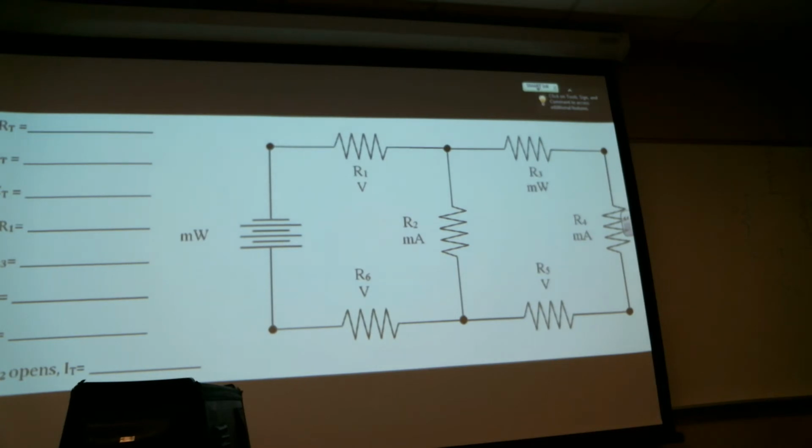But I've seen one where there was no node, and then over here these 2 were nodes, and you had to do this and that. You'll see lines that cross each other, and if they don't draw a dot, they're not touching. Normally, we draw a little hump over it, and that's supposed to indicate that it jumps over. But I always question it when there's no little dot and they cross each other. You have to assume. Then I start looking around, and if they've got dots in other locations, then it looks like it. But most of the time, you'll see a little bridge.